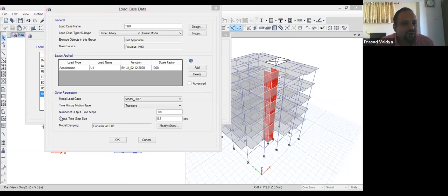So for example, if you have, say, for this time history 26,706 acceleration points with an interval of 0.005, that is roughly 134 seconds. You add to that 134 seconds five times your first modal time period.